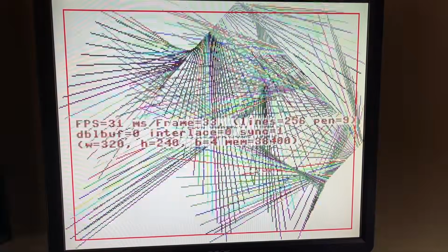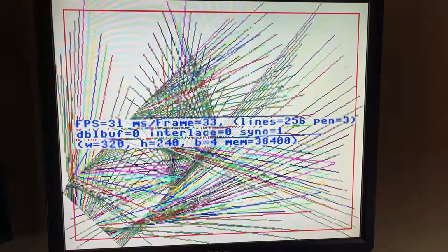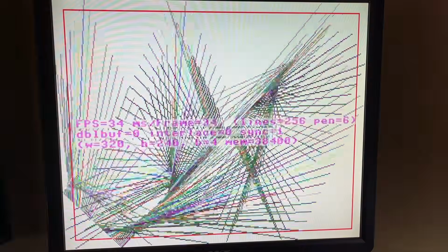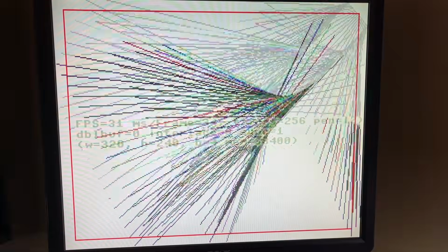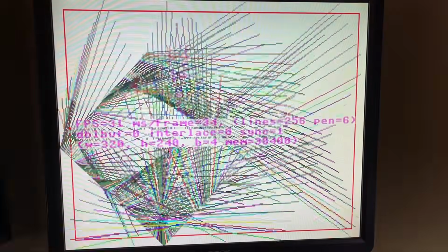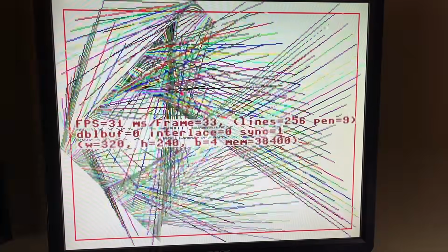We're going to create another frame of memory that we draw on while the first frame, the show frame, is being displayed by Core 1. So while Core 1 is displaying one frame of memory, Core 0 will be drawing on the other one. So there'll be no interference between the two cores. And then when we're done drawing, we'll swap. We'll put the drawn frame in the foreground, and that will be our display memory or show memory, and our memory that we're drawing on will go into the background. So these two frames will just swap back and forth. So let's turn on double buffering and see that in play.